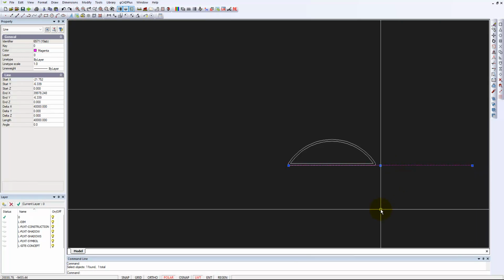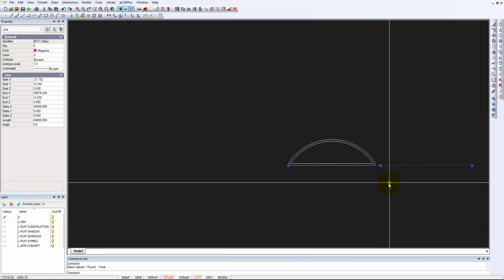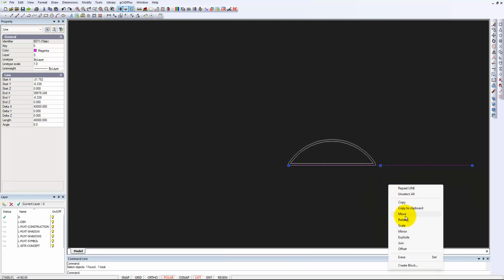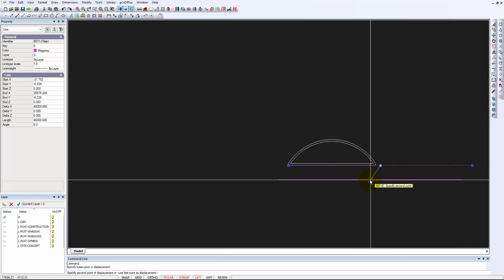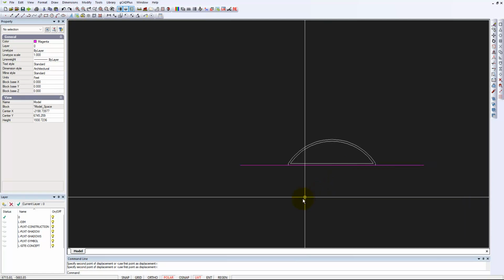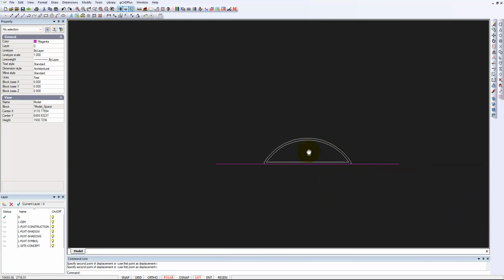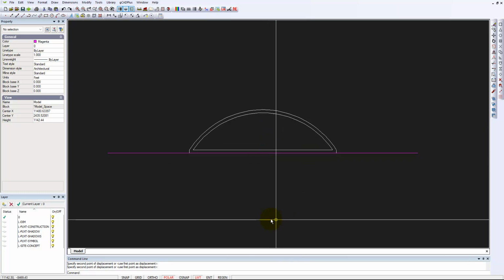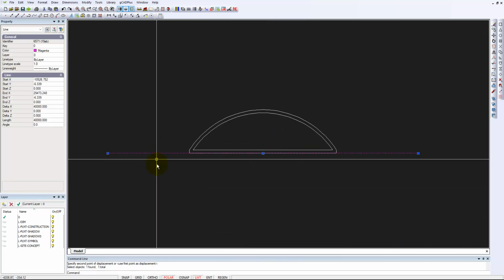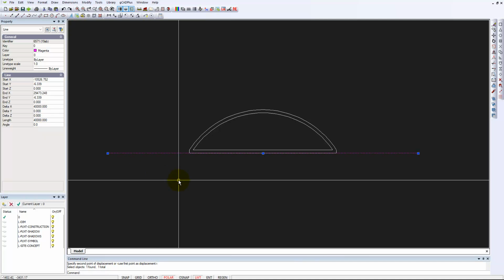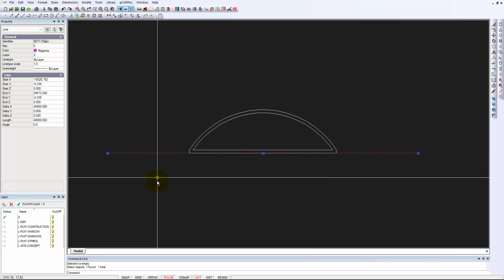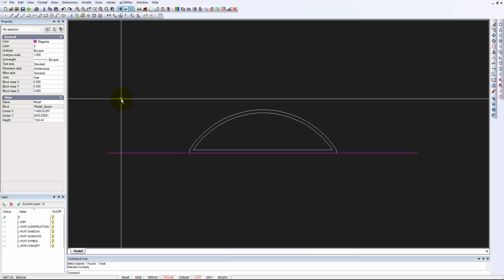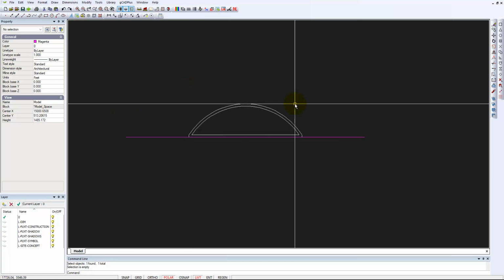Now, I'd be inclined to move that line from its midpoint to the midpoint of there. So now the garden bed sits in the correct position, and we check ourselves again by clicking here, and it's 40 meters long. So there's no need to scale things. You just use the properties box to change the properties of the entity that you throw in.